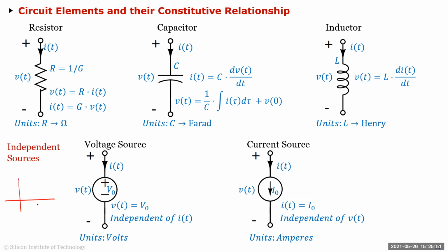So if I draw the IV characteristics for this, then it's basically a line, V from minus infinity to infinity. Sorry, this is the ideal voltage source. So if this is V, this is I, then your IV characteristics is this, going from minus infinity to plus infinity of I. So essentially it says no matter what the current is flowing through it, the potential difference between these two points is always V, whatever V you have chosen, V or V of t.